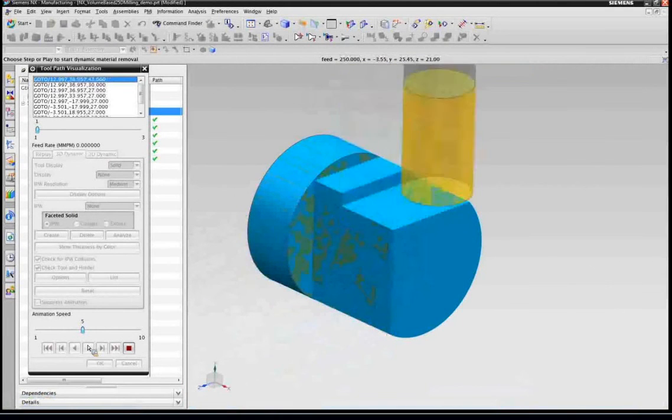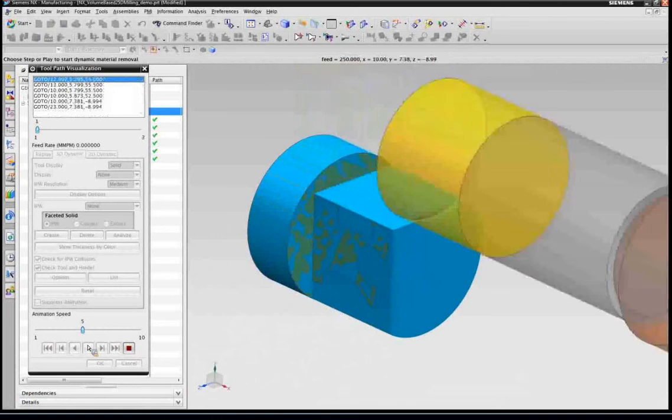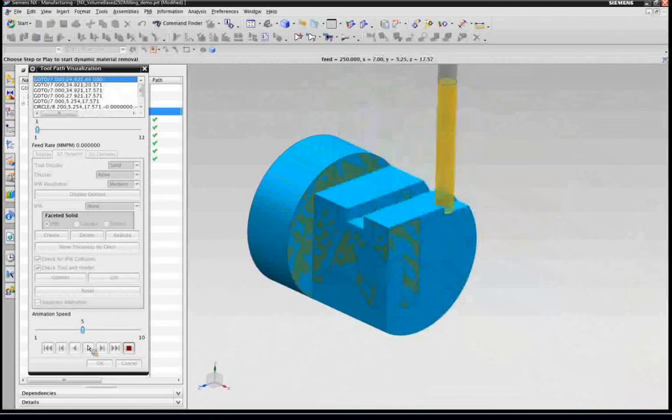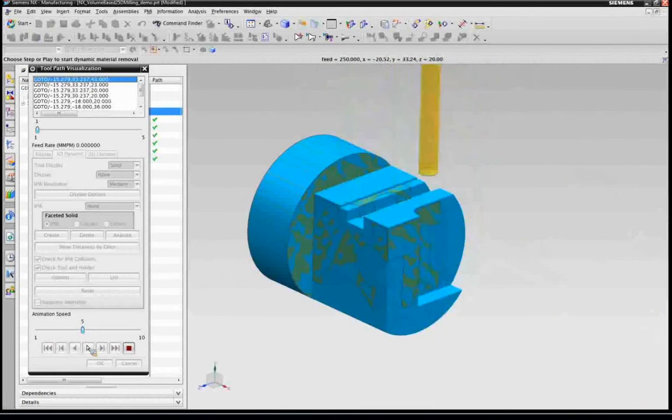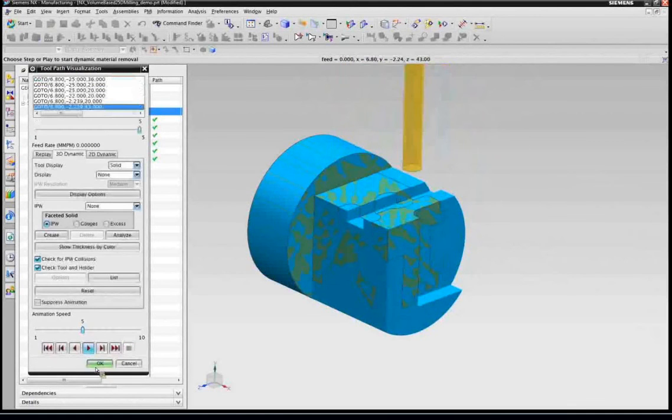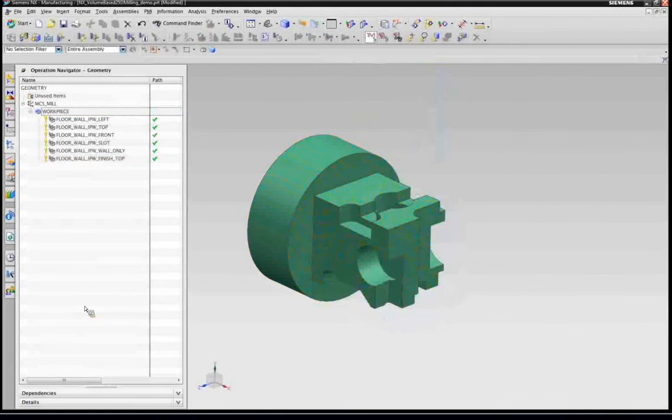Showed you just 2 before. You'll see the very big toolpath that does a single pass, 2 cuts through the slot, the no floor operation that goes a little bit deeper, and the finishing of the top. Now, we can do a lot more complex operations. We can do slanted walls, we can do filleted tools, we can do undercutting.